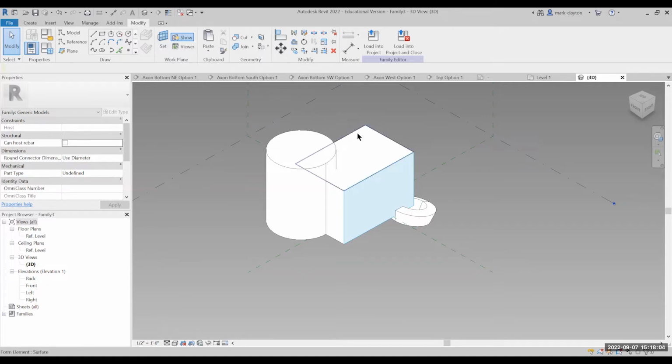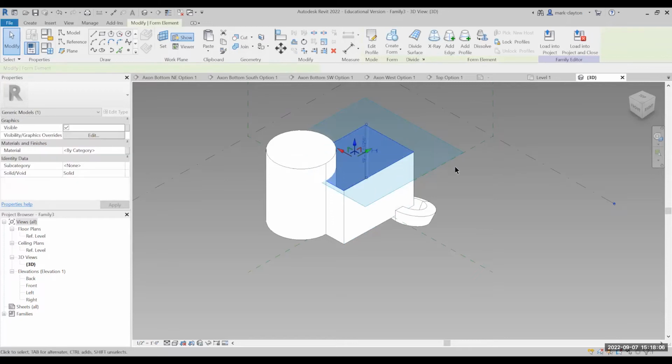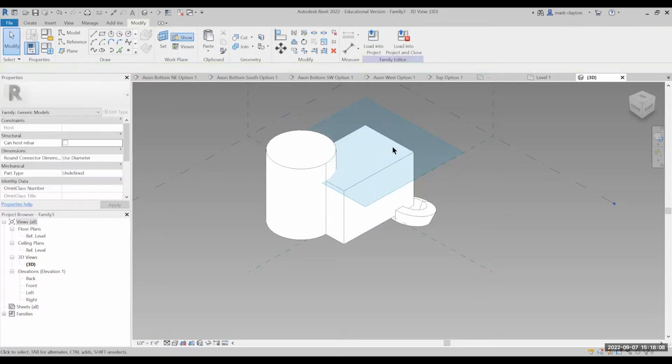Okay. So let's set the top to be my drawing plane. And all I have to do is click on that face and it moves the drawing plane up there. And then I'm going to draw an axis. Well, let me show you that it doesn't matter what order you draw things, but I am going to use a different tool here. I'm going to use the spline through points. The spline through points is an incredibly powerful tool, and get used to it, rely upon it.